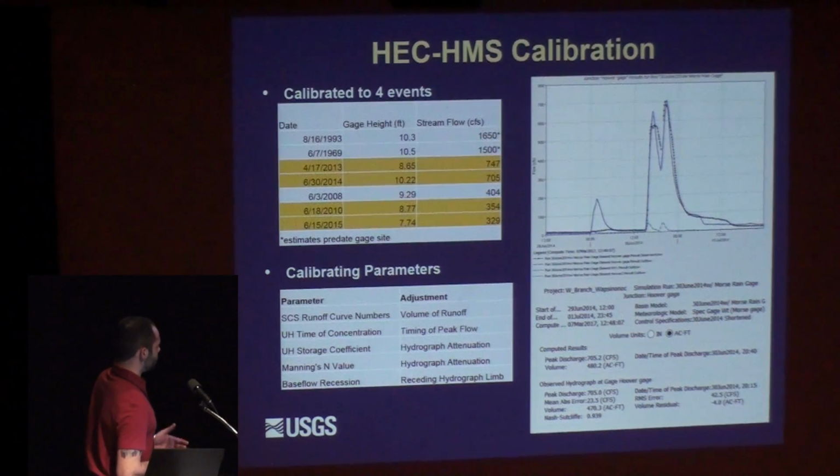So you have to change some of your parameters to match the hydrograph to get your volume, your total volume coming off the watershed. You want to match your peaks of the hydrograph and also the timing of the rising and receding limbs.